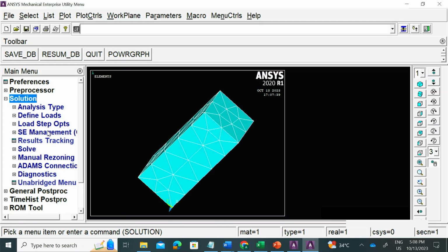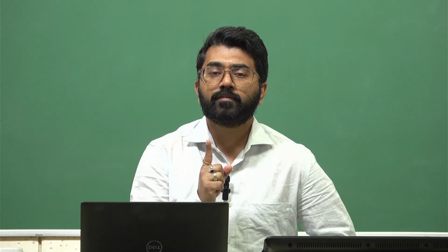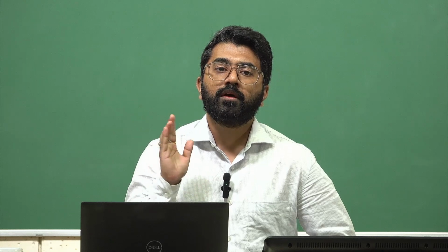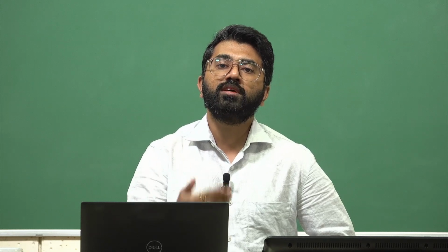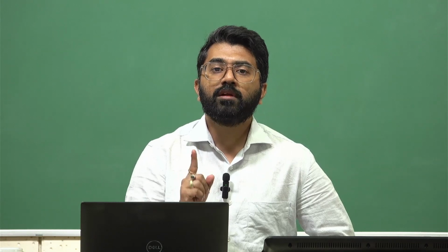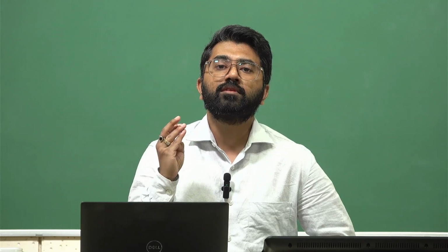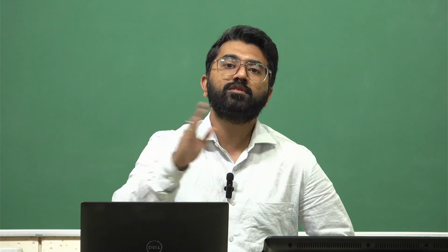Is the load and constraint only to be applied after meshing? Not necessarily. You can apply this load and constraint beforehand, before meshing also. But one thing to be noticed: where are you trying to apply the loads and constraints? This is the point of concern. There are two things, and the terminology we are going to use is like this. One is the geometrical model and one is the mesh. Mesh will only happen after you have meshed the geometrical model. Geometrical model has key points, lines, areas and volumes. The mesh has elements and nodes. These are the two different classifications.